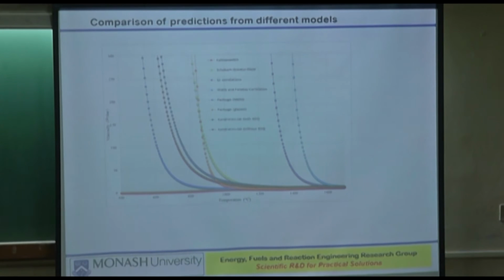Now, in a gasifier, you have say 40–50% hydrogen sometimes. At least we got for fluidized bed gasification 25% CO, 25% hydrogen. Those are right in the middle of the lower and the upper explosibility limits of hydrogen, so you cannot use it.